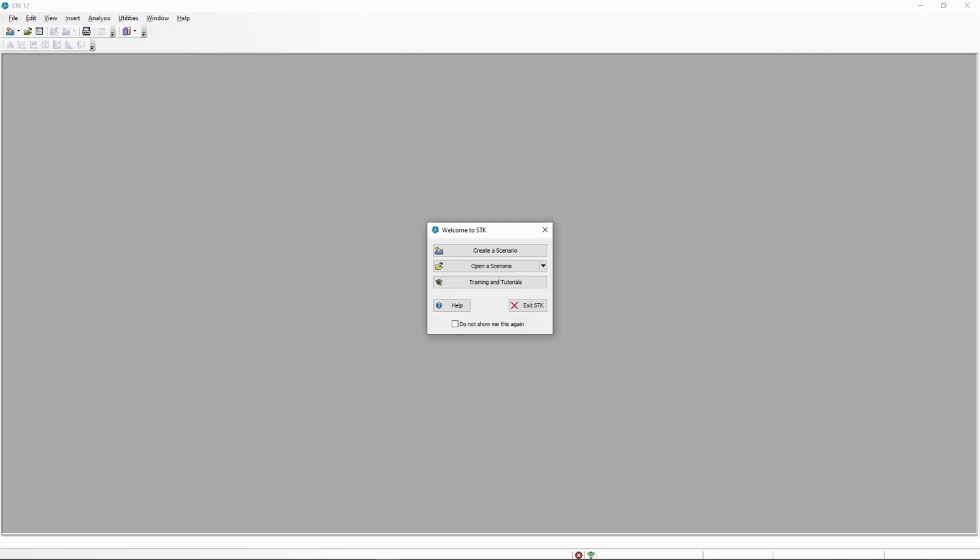Engineers and operators often need to determine the times one object can access or see another object. In addition, they need to impose constraints on accesses between objects to define what constitutes a valid access. These constraints are numerous, such as elevation angle, sunlight or umbra restrictions, gimbal speed, range, etc. They also require the ability to create reports and graphs that summarize static data or show dynamic data during animation. Building on your fundamental understanding of STK, you will learn two important tools to solve this problem: the access tool and the report and graph manager.